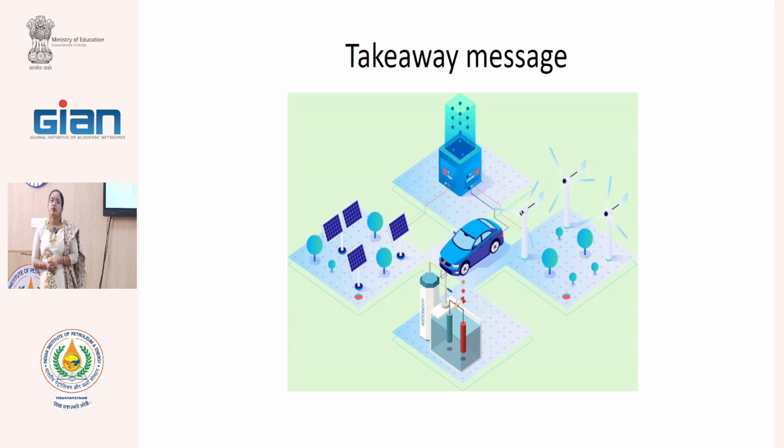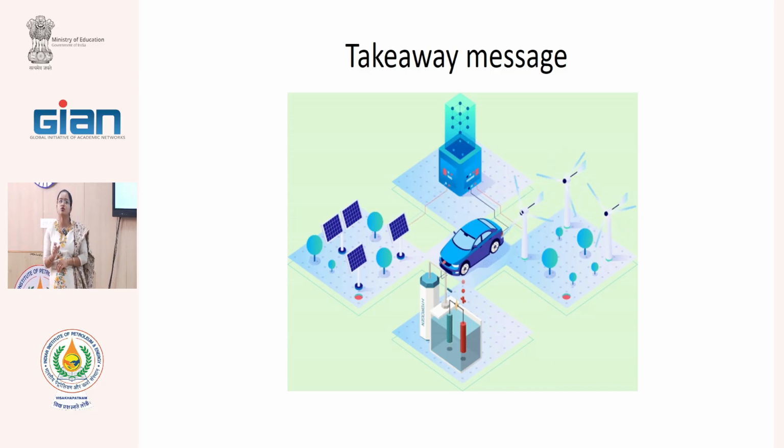One problem is that. Second, it must be experimentally determined how much thickness of PTFE is causing how much loss in your power generation output. So you should measure the activation energy and the reaction rate with different thicknesses of PTFE. Only then can you apply a coating of PTFE, or otherwise you should look for other options, like a completely different cathode material that is less hygroscopic. That can be another option.